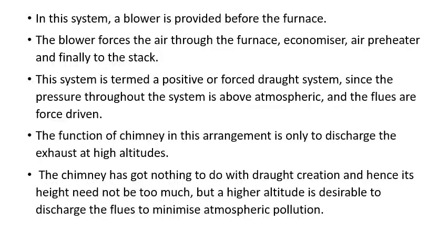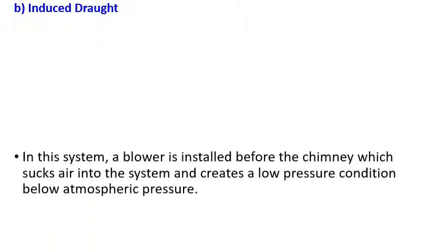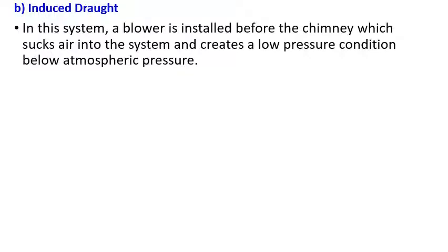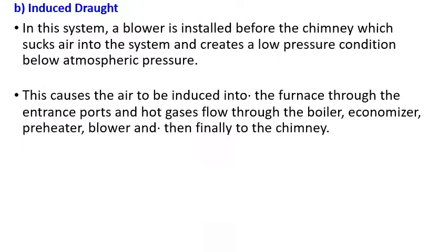The chimney has got nothing to do with the draught creation, hence the height need not be too much compared to the natural draught. What is induced draught? Let us understand. If a blower or a fan is introduced after the boiler and there is no fan before the boiler, then this is an induced draft system.